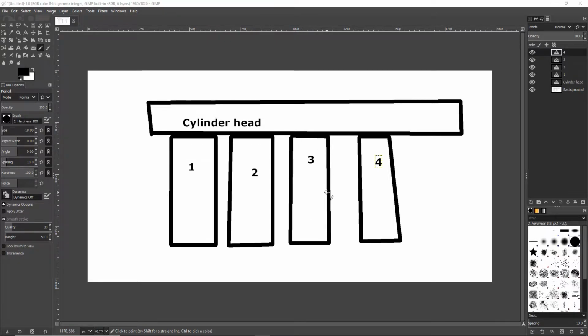But anyway, if we wanted to figure out the displacement of an engine, we would do it this way. We would put the piston in bottom dead center, and let's pretend we took some fluid, whatever you like, Dr. Pepper, and we filled this cylinder all the way to the top, and this one, and this one, and this one. So now we have displaced a volume. Let's take all of that liquid and pour it into a measuring cup over here.